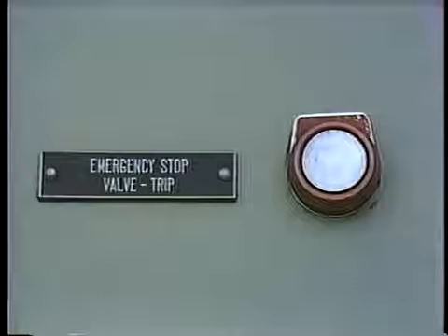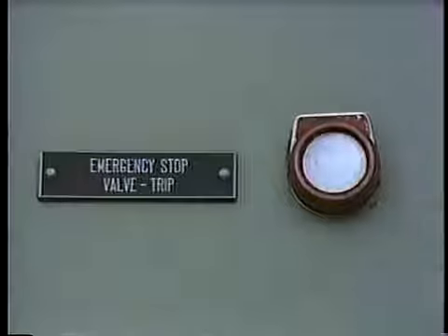Once fuel flow has been stopped and the boiler purged, most procedures will require the operator to return the boiler to normal operation as rapidly as circumstances will allow. This is to prevent steam pressure from dropping low enough to trip the turbine. Now, in the event that the prevailing conditions make it impossible to return the boiler to normal operation, then the operator must take the appropriate action to trip the turbine.